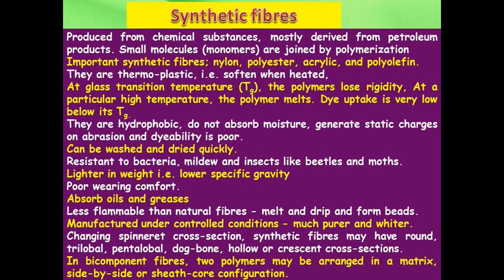The dye uptake is also very low below its Tg. They are hydrophobic, do not absorb moisture, generate static charges on abrasion and durability is poor. They can be washed and dried quickly. Resistance to bacteria, mildew and insects like beetles and moths is quite high. Lighter in weight, that is, they have low specific gravity, poor wearing comfort, absorb oils and greases, are less flammable than natural fiber, and melt and drip and form beads.